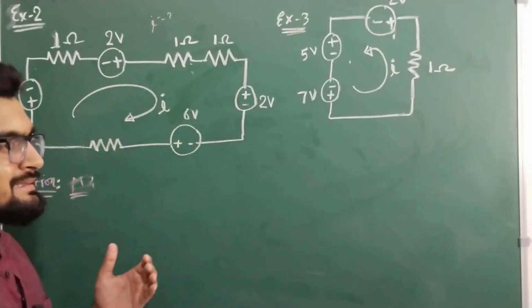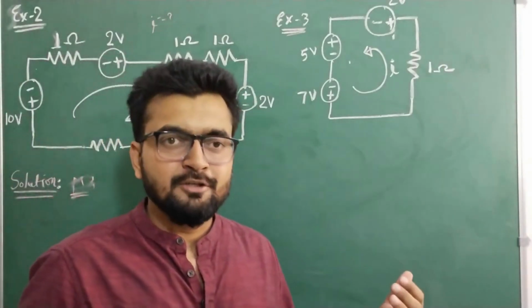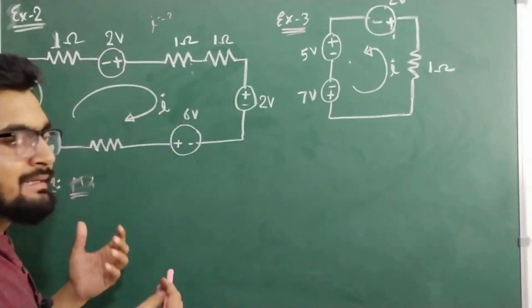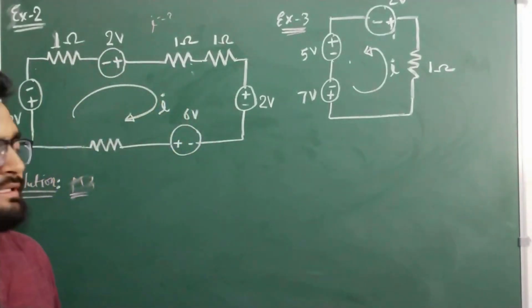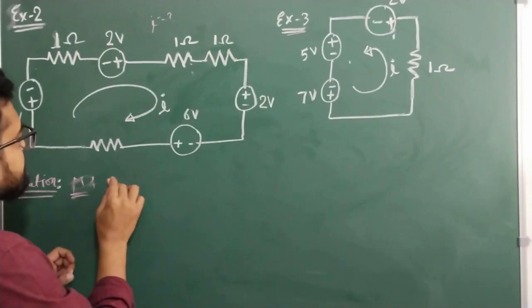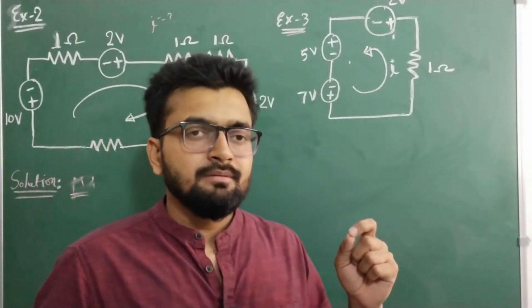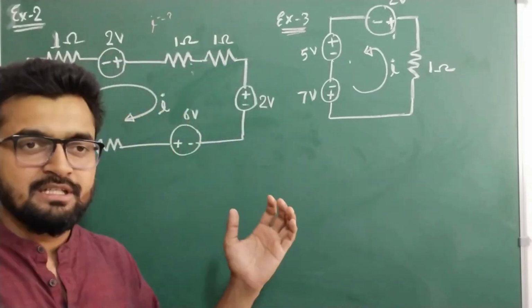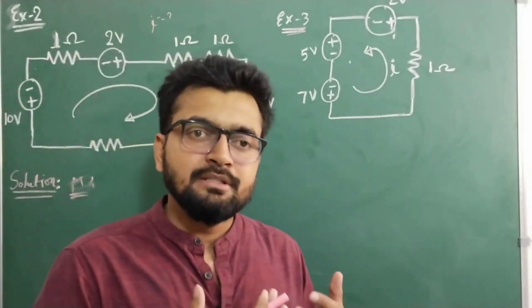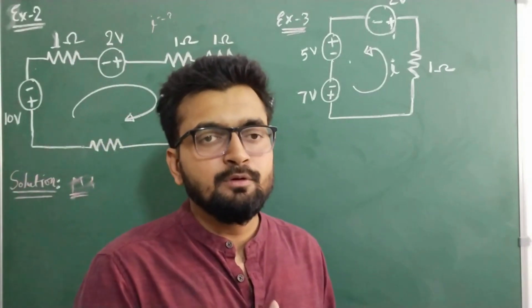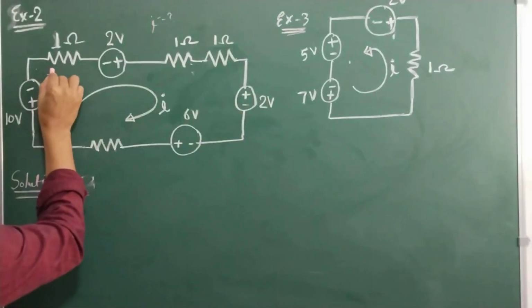What we know is that in the direction of current the potential drops, right? We have already discussed this extensively in the last class. And why does it drop? Because the charge which passes through the resistor decreases its potential energy, and thereby the voltage drops. So the first step is to assign the polarity.